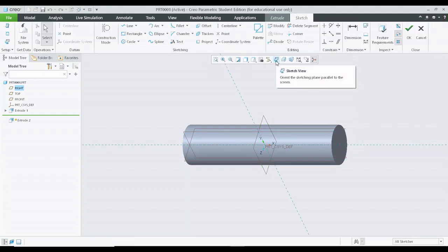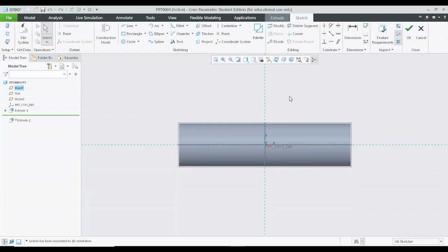After that, let me click on the sketch view. So you can see that the previous extrusion is already visible. So this was the previous step that we have worked. Now we are into the next step of the creation of any model. Clear? So right now I want another circle. Actually, let me just try to use a rectangle otherwise. And I am trying to choose a center rectangle, and let me originate the rectangle from the center.